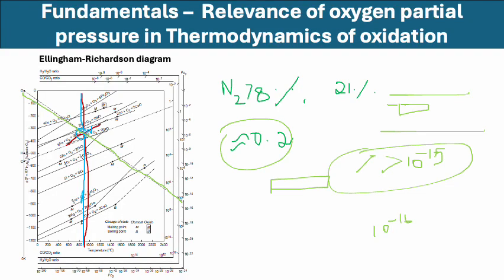So what I will need to do is, if I understand the kinetics and if I know the growth law, then I can use that to predict whether the oxide scale will grow to a particular thickness, whether my structure can structurally remain intact for the given service time. So that is the question that we can answer. So for that we will use parabolic kinetics.